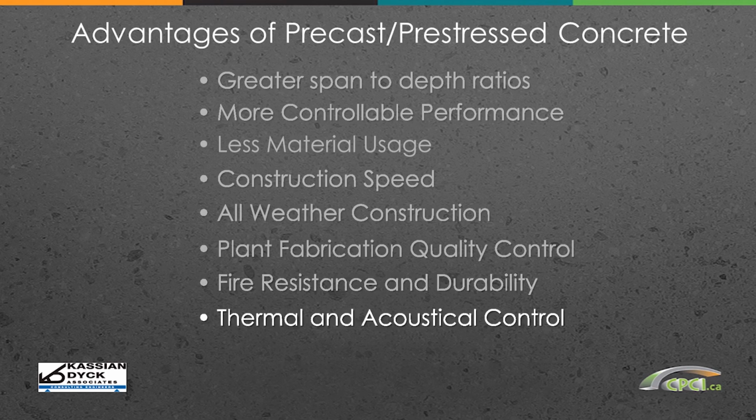Precast provides excellent thermal and acoustical control, providing pleasant work and living conditions for users and inhabitants. On the project site, precast concrete construction minimizes site impact by casting precast components off-site and can make use of just-in-time delivery with small erection crews as compared to other systems. That reduces the number of personnel and trades on site, which reduces safety and other risks at the job site.